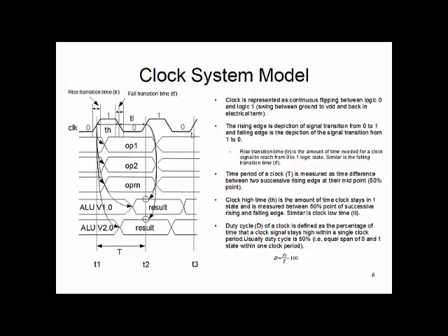The other important part here is these arrows. Sometimes they are given in the diagram, sometimes they are implicit, and people don't want to draw them because they may give the timing diagram a cluttering effect, like too many arrows going on here, right? But if it is present, what it means is that these changes are related to this time point.